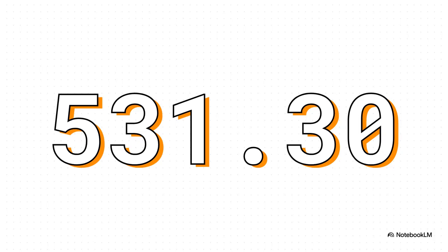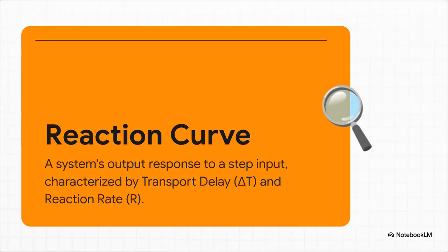We just do the same thing for the other formulas in the table to get our starting Ki and Kd values too. Okay, now let's switch gears to that other Ziegler-Nichols approach, the safer open-loop method. Instead of pushing the system to its limit, we just give it one nudge and watch what happens. Think of it like tapping a bowling ball.